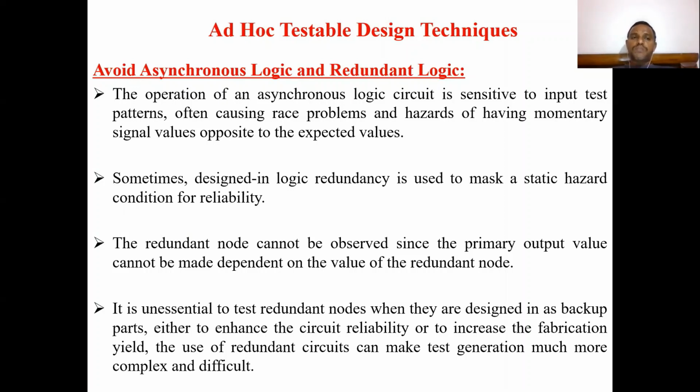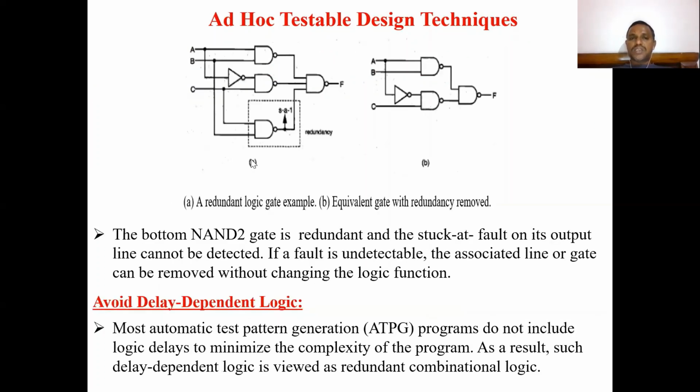That's why it is better to avoid asynchronous logic and redundant logic at the time of testing. The use of redundant circuits can make test generation much more complex and difficult. So we have to avoid asynchronous logic and redundant logic in the circuit under test.